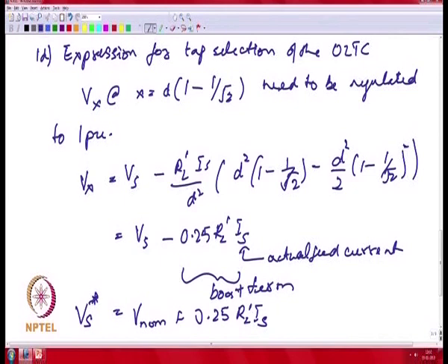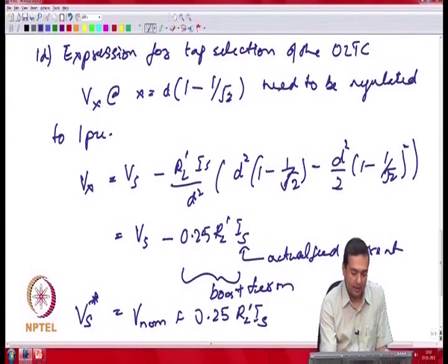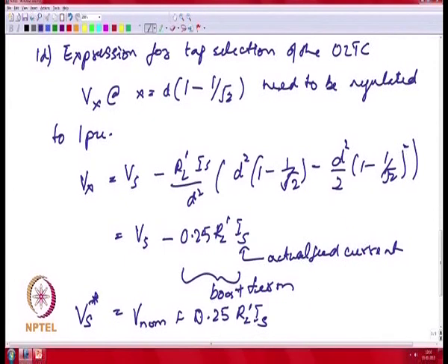and here we are assuming that in an actual substation there are multiple feeders. So, we are also assuming that all the feeders have similar characteristics over the day. So, it is not just that one particular feeder has load, the other has no load. So, it is a similar type of consumption depending on the time of the day, etc., and you want to actually provide a boost action across all the feeders that go out from the substation.